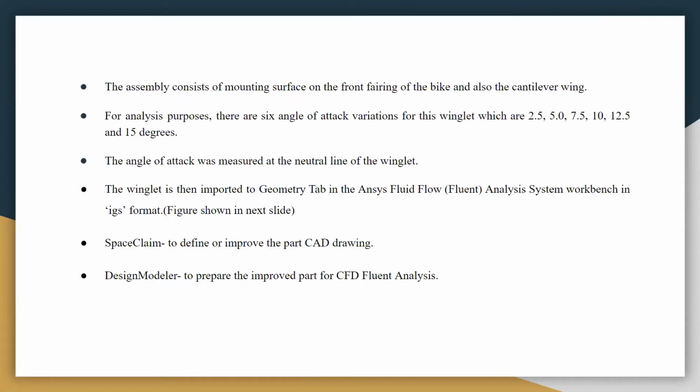Inside the geometry tab, there are 2 workbenches, which are SpaceClaim and also Design Modeler. We use SpaceClaim to define or improve the part CAD drawing because our CAD drawing consists of multiple joints and surfaces. So we use SpaceClaim to combine all the surfaces into one solid.